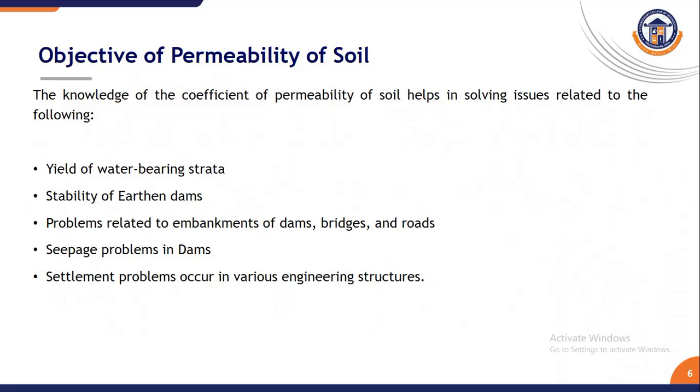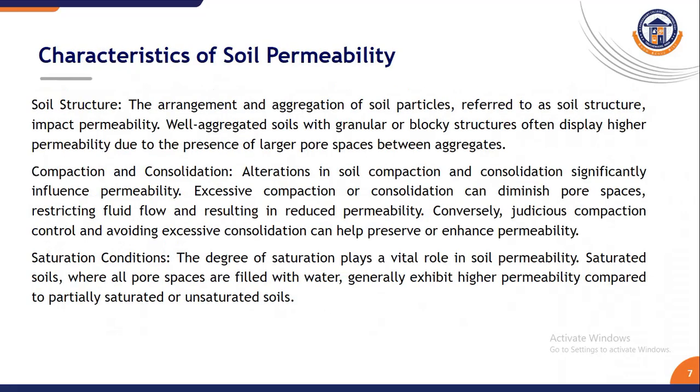The main objectives are to estimate the groundwater flow rate, to analyze the seepage in dams, to evaluate the foundation drainage, to predict the settlement rate, to design the filter and drain, to estimate the yield of aquifers and to determine the seepage problem in dams. Okay, here all the objectives of permeability of soil are very important.